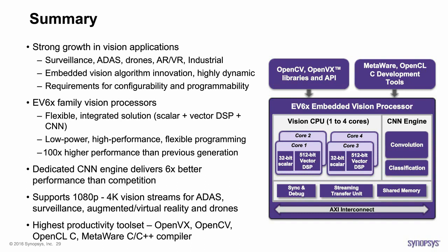So cache coherency is supported for the L1 cache on the Vision CPU cores, and that's of course configurable as well as the I/O coherency, so that you can keep the information between the different cores coherent as you run the processing of the algorithms, whatever the Vision algorithm you're running.